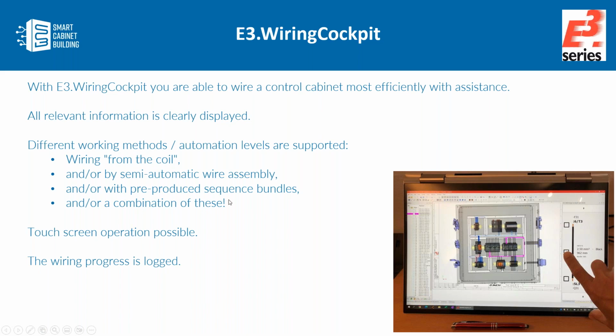from the Komax machine. And as well, because that's normal life, this also works in combination, because if you have maybe a Komax machine and 80% of your wires are coming from the Komax machine with the sequenced bundles, then you normally have some more wires with higher cross sections, or very small cross sections, that you cannot produce on the Komax machines.